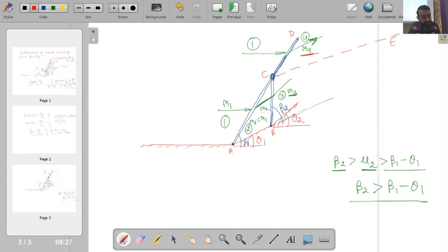Okay, so this particular line I will call the slip line. But we have also seen in our previous lecture that if I have the presence of a slip line, then in the upstream and downstream of the slip line, so say this is region 4 above the slip line and region 3 below the slip line, ultimately for a straight slip line to exist, P3 has to be equal to P4.